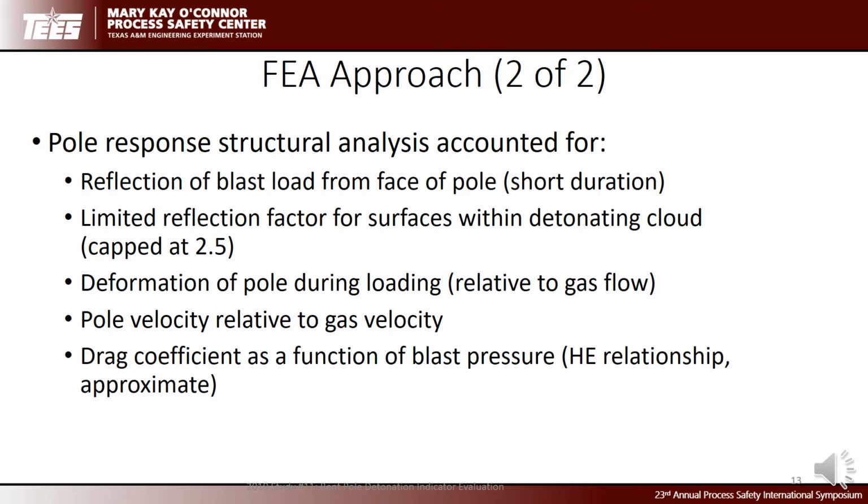We included deformation of the pole, that is, as the pole begins to deform and bend over while you're changing the nature of the drag loading relative to the gas flow. We also included the velocity at which the pole was going over, since that changes the relative velocity of the gas rushing by it. And we varied the drag coefficient. We varied it as a function of blast pressure using a high explosive relationship, which is admittedly approximate but captures the effect.